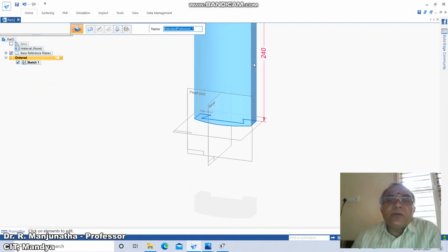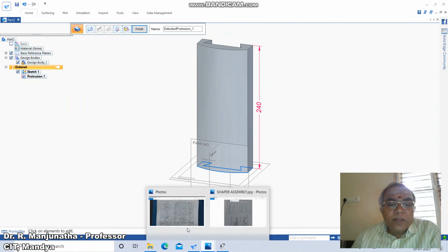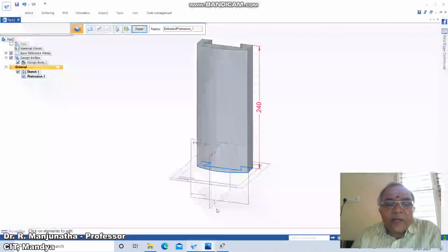So take it up to the top side. So now you just have a finish. Now once you get this, next come down to this portion. Again there is a slot here. This slot is at a distance of 5 mm from here, and create these two. To do that, go to, and you take the distance of 5 mm from the parallel plane.